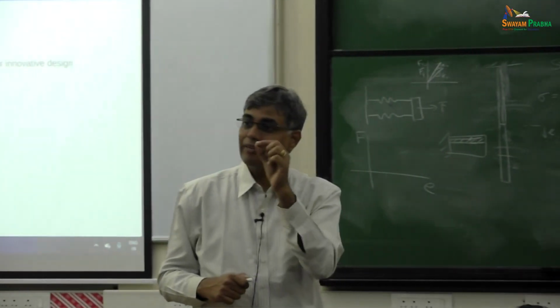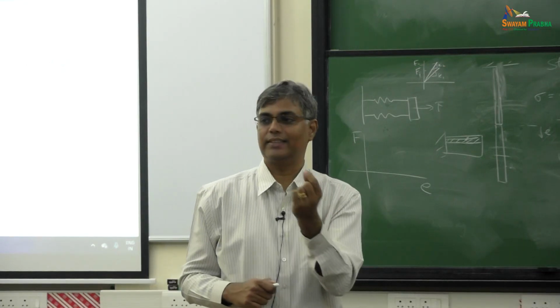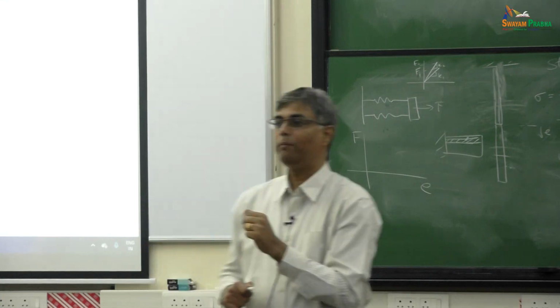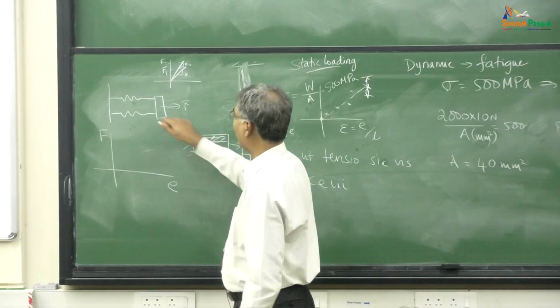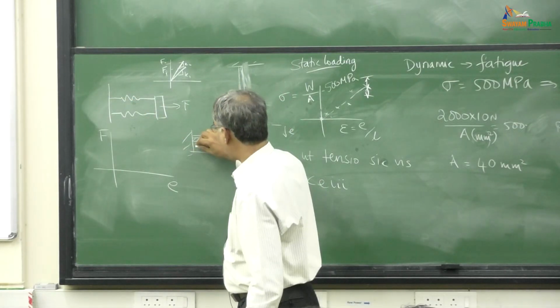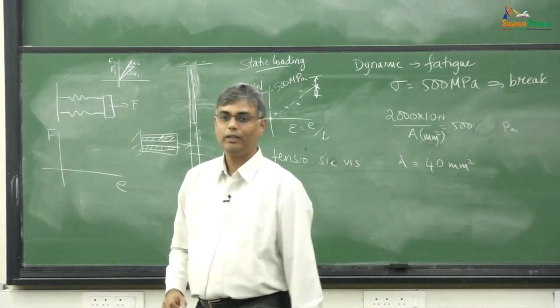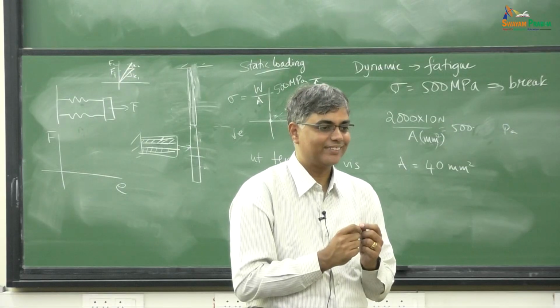Because the chalk piece will have some defects, some voids, some pre-existing cracks, which are slightly different in each of those. So what I'm doing is, I'm going to model this bar as a bunch of parallel springs, in this case only two, because 2 is easy to do, each of them with slightly different properties.